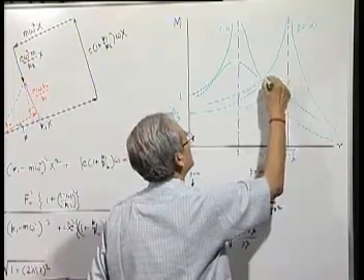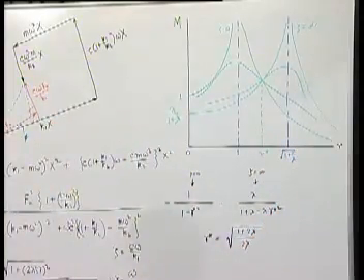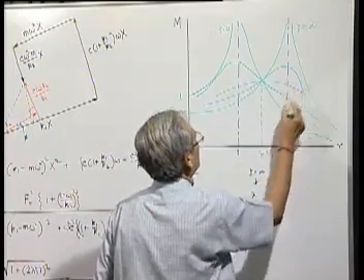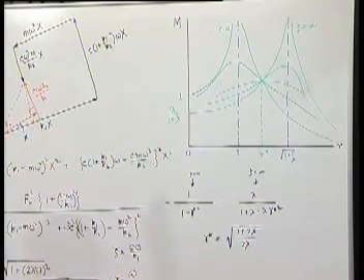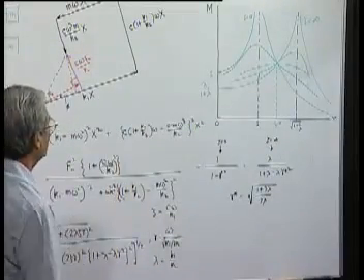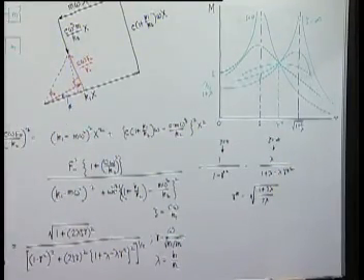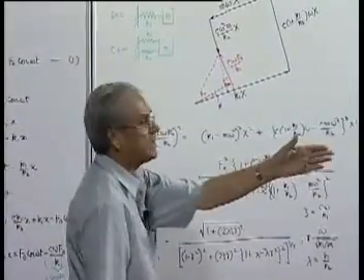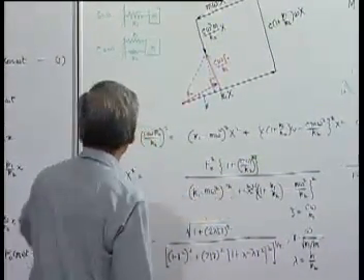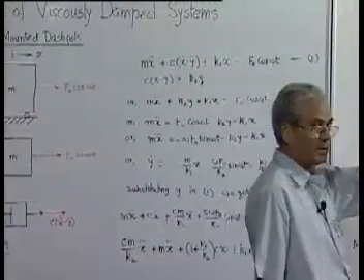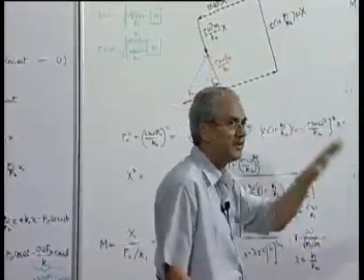So, it has to be something like this. You can easily solve for different values of zeta, and the curve has to always pass through that R star. So, the best value will be where this is the maximum value. With magnification factor for which at this value of R star, we can then show the peak value will be independent of zeta. So, that is a case where you will find that the curves of deflection of the system for different values of zeta will have to pass through the whole range of forcing frequency, as forcing frequency may vary. That means it will be something like this. Over the whole range, the peak value of the deformation or displacement will be kept to a minimum.